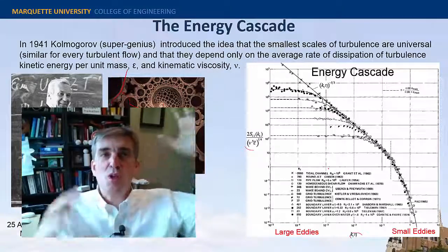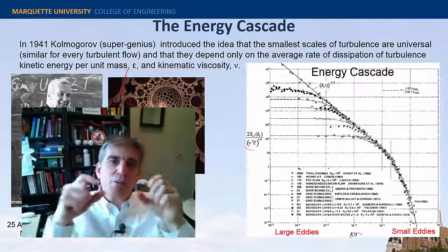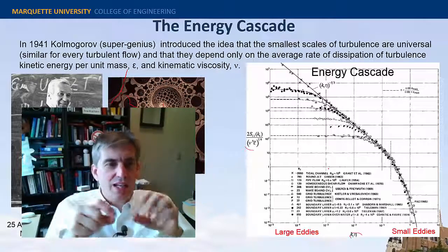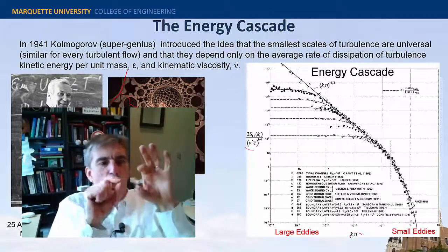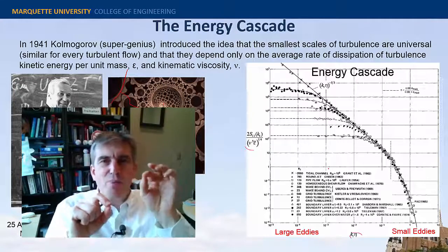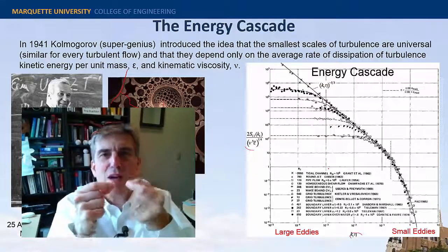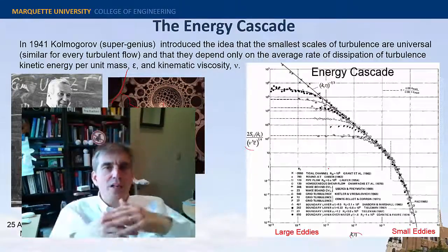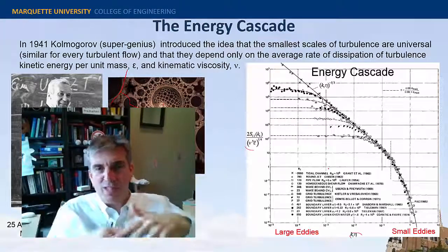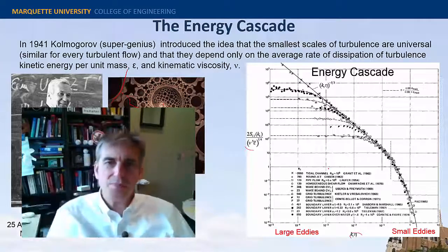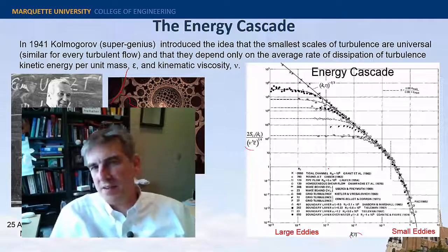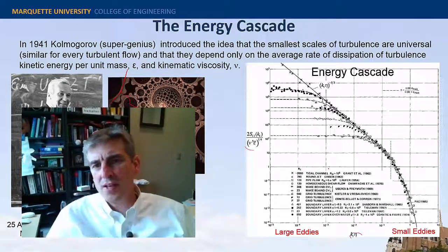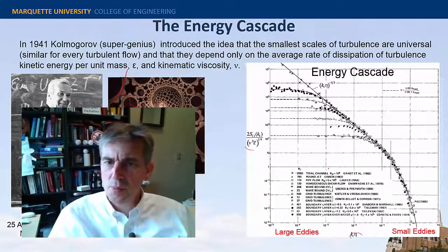And the reason we look at these super large fluid flows is because we can really get in there with the scales. If you did this in a wind tunnel, the Kolmogorov scale might be so tiny that it's smaller than the hot wire, so you can't make a measurement of the Kolmogorov scale. But if we look at really large turbulent flows, like meteorological scale turbulent flows, we have a chance of actually making measurements all the way down to the Kolmogorov scale.